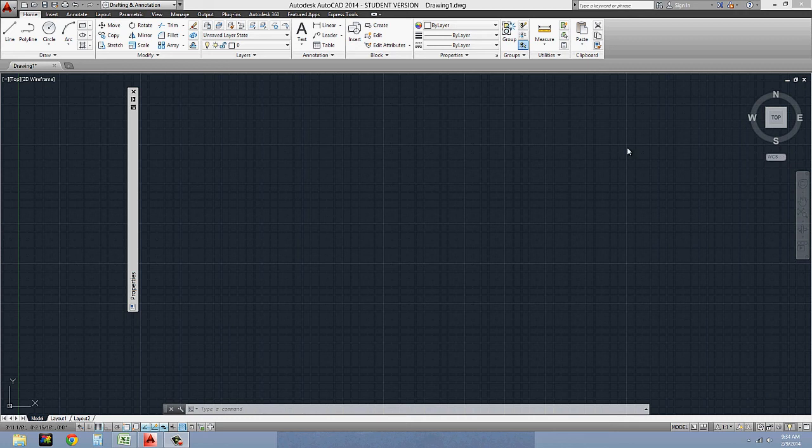Now, what I'm going to do is introduce the concept of XREFs, and we're not really going to understand it until we start to build our sheet files. So what I did is I started off with just using a regular AutoCAD drawing. I opened it up not using the template that we created, because it's not technically a plan drawing. What I did to begin with is make sure that my units were architectural, and you'll see that when I open my file I only have layer 0.